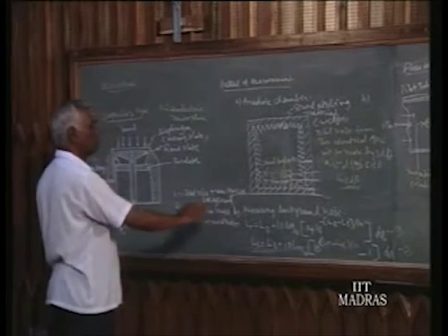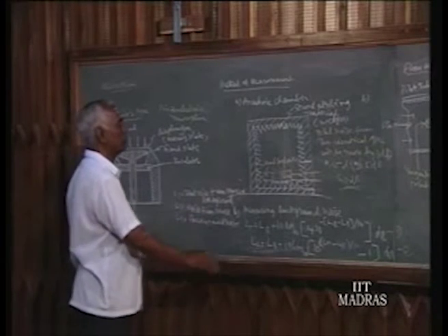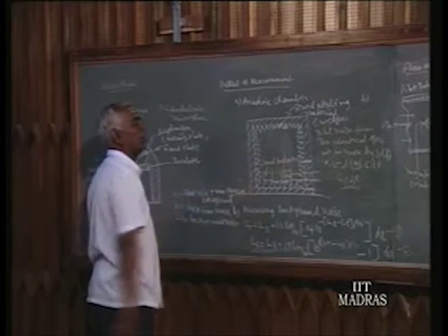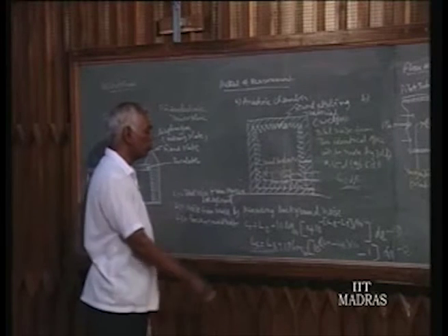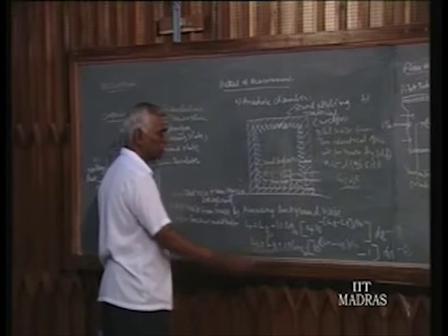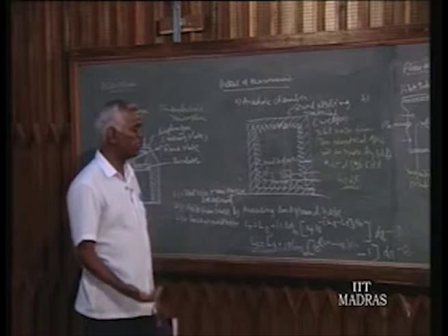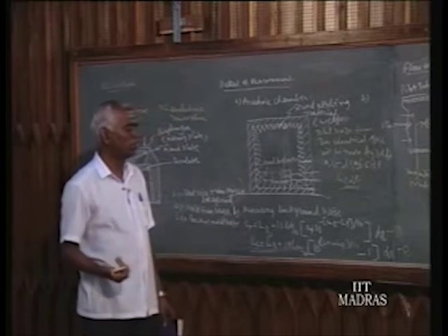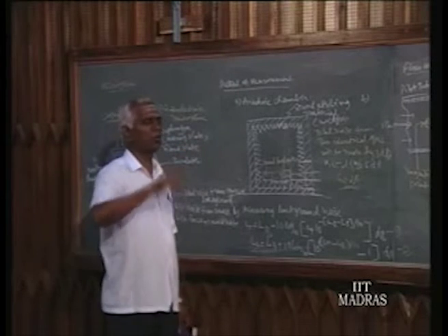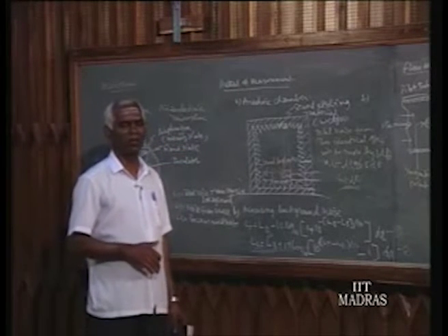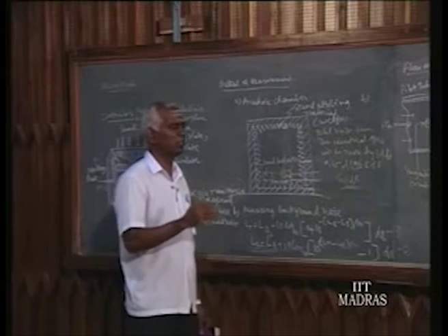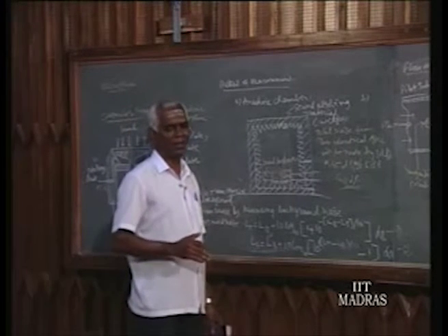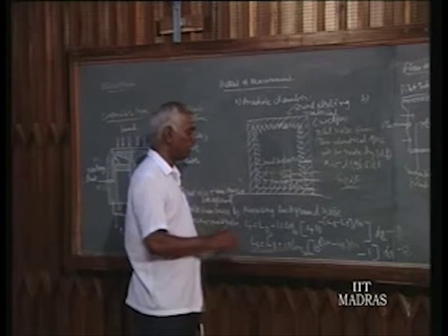That is the easier way of making measurements of noise instead of the anechoic chamber, which is costlier. But you should have control over the background noise, and that is sometimes very tough. That is why in our laboratory, when we want to make such noise measurements, we come at midnight, so that there will be less noise around, only noise from the birds and the wind may be there, but it may be more or less constant, and then we make measurements.